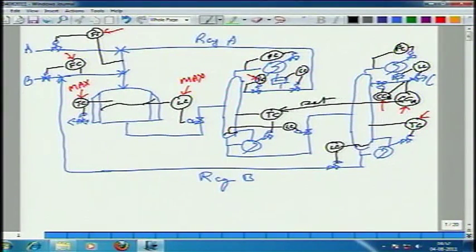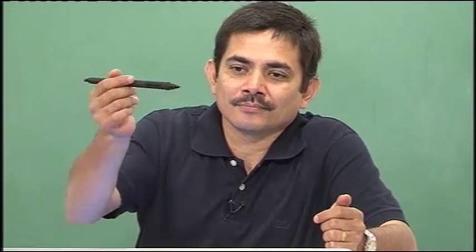I am going to take this total B reading, multiply it by a number which is close to 1, but not exactly 1, maybe 1.1, 1.2, maybe 0.9, 0.8, and that will be the set point for this controller. Now, the operator is setting this ratio set point and the total B set point. He is still setting 8 things, but this is a more reasonable way of doing things. It automatically gets you close.